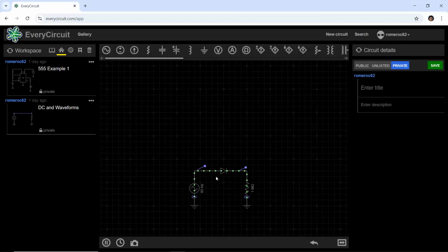Now you can see. Okay, very good. Space, rewind. I want to see the voltage here on this node. Click here on this node and click show waveform. And click on this another node, click show waveform.